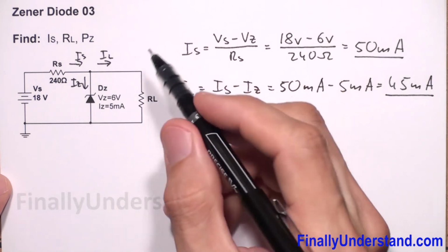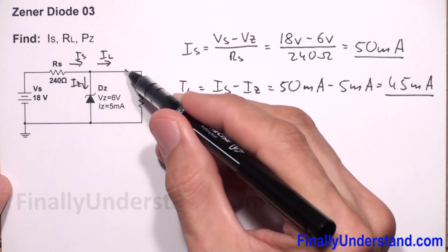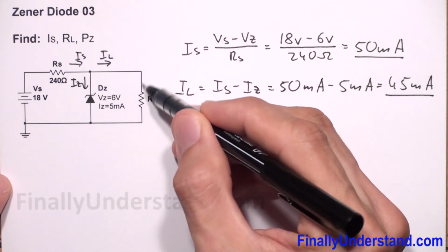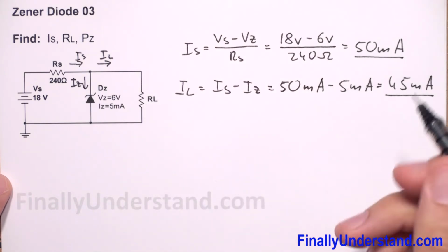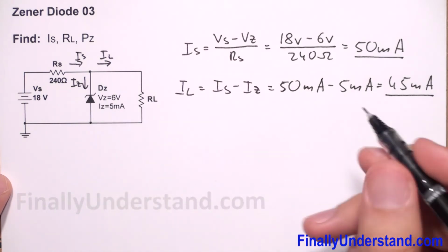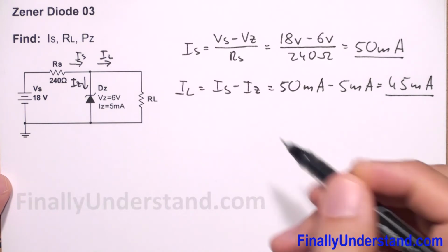And let me remind you, if you want to measure the current which goes through the resistor, you're supposed to always open the circuit and connect the ammeter in series with this resistor. Okay, this is just extra information for you because probably you are going to test this circuit in the lab. So just for your future reference, I'm just giving you this information.